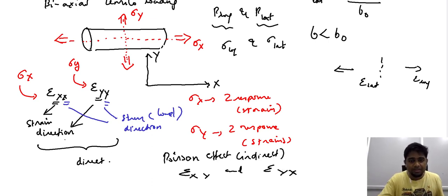The principal takeaway of this consideration of biaxial tensile loading is that when you increase the loading, or when you convolute the mechanical condition that we impose on a material, when we shift from uniaxial tensile loading to biaxial tensile loading, the response that we observe correspondingly varies. We will try to unify these different responses in the subsequent lecture.